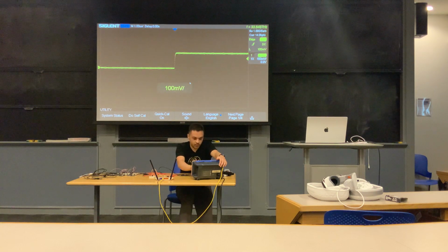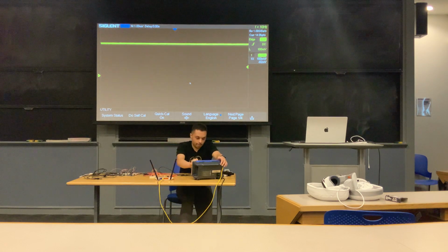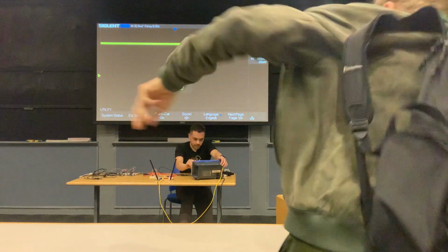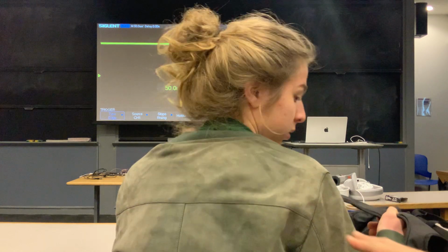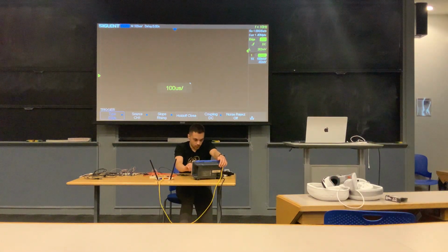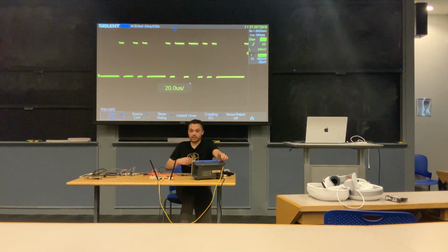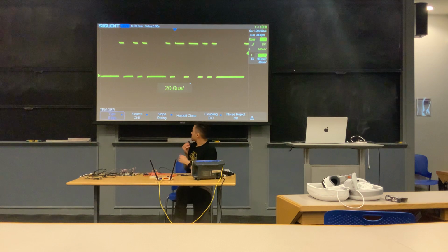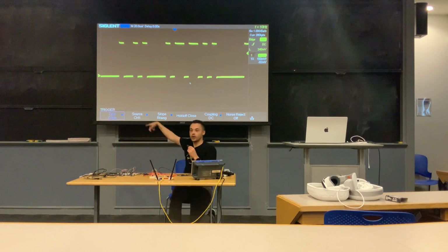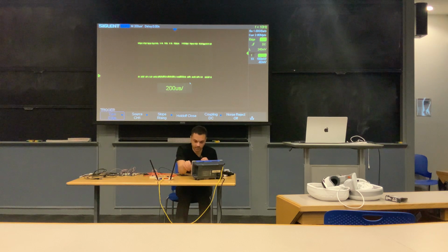I'll go ahead and bring this up, and let's see if we can see what's being sent here. So clearly some data is being sent to this line. And so what I'm going to do is zoom out for us and set up a trigger so that when the voltage spikes, it'll actually capture that signal for us. And you can see, okay, we've just got some data here. So this is clearly some type of data, some type of communication. You can see we're going from 0 to 1 up and down. Right? So let's see if we can figure out what this protocol is and what's being sent on the wire.